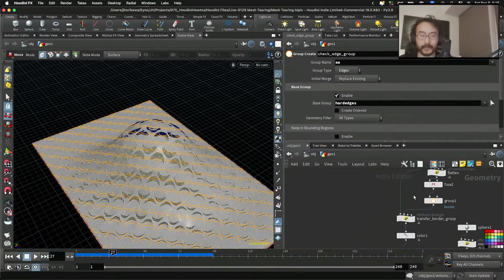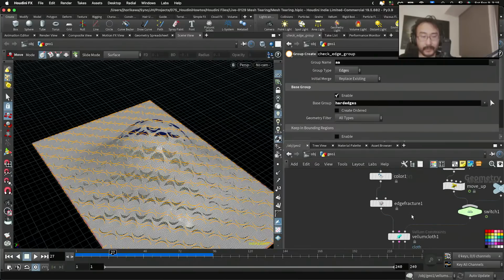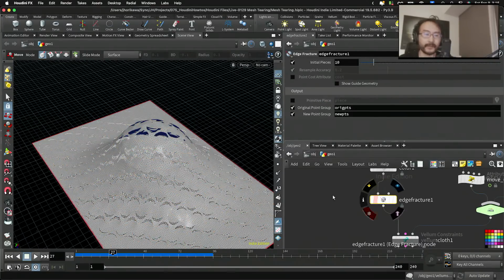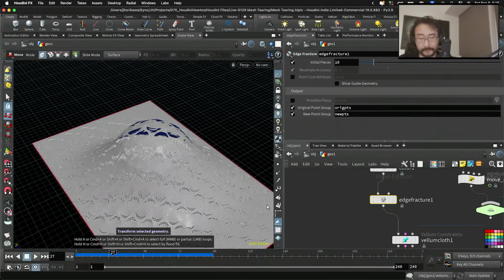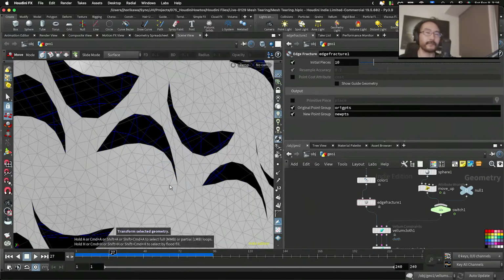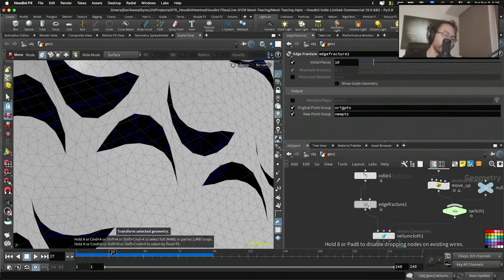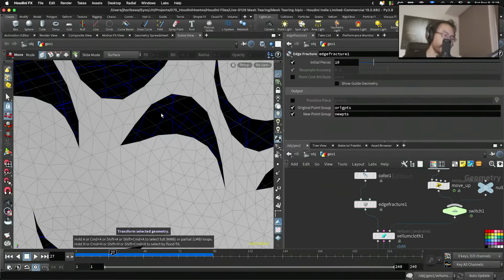The edge fracture only creates a special edge group for Vellum, which can only be collapsed or ripped by the Vellum shape, but this doesn't really split the shape. It just converts each edge to some weak glue edge, which only works on Vellum. Geometrically, all the mesh is still connected even if you have this, except for these open ones.